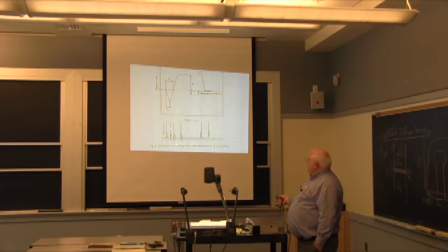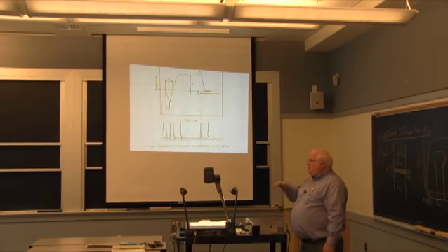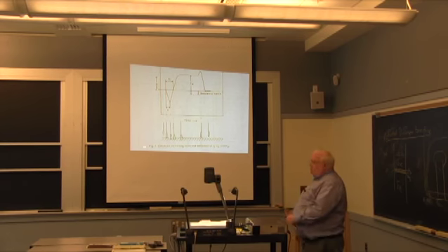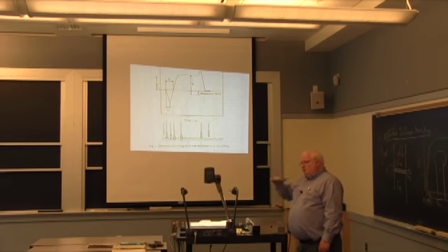You can do it in a system where everything is hot, or you can do it where it's cold. Typically, the wire is cold because this is a practical test. You're going to be putting your circuit board into the system cold, and the bath is going to be hot. So the whole thing is in temperature gradients. But these $50,000 machines can do various things. But you're trying to simulate typically what's going to happen in what we call wave soldering.